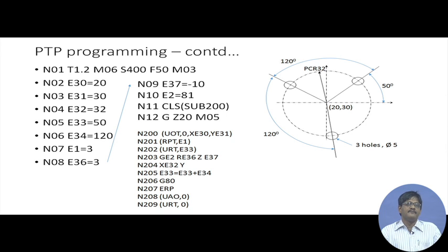These are very strictly handled, so that E30 can only be assigned such dimensions referring to coordinate values. So, E30 is 20, E31 is 30. We have to designate these values in the initial program. So, in the main program we first have the designation of different E values. E32 is 32. What is that? The pitch circle radius. It is sometimes referred to as grid radius.